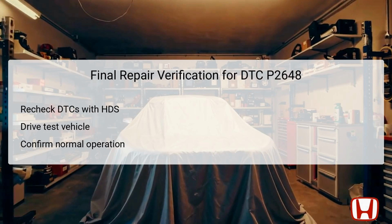After completing the repairs associated with DTC P2648, it is crucial to recheck the DTCs using the HDS system to ensure that the issue has been resolved. This provides confirmation that no new error codes are present and that the previous DTC has been cleared. Subsequently, a drive test should be conducted to confirm that the vehicle is now operating normally without any performance issues or warning lights. This step serves as a final confirmation that repairs were indeed successful and have restored the system to its intended operational state.